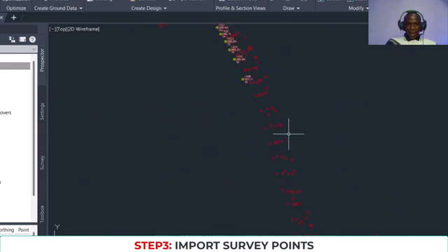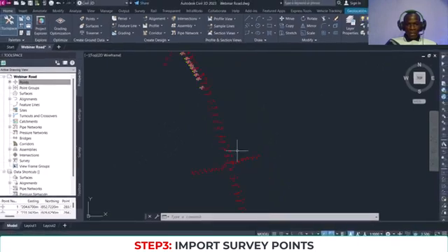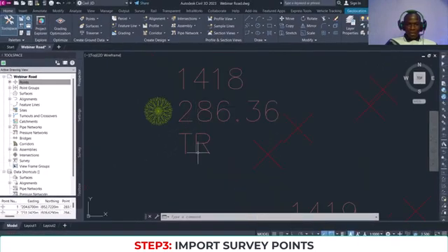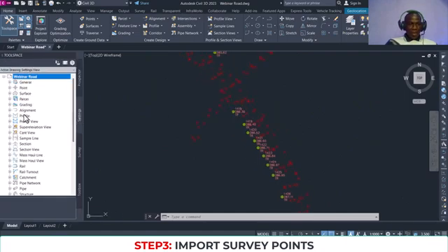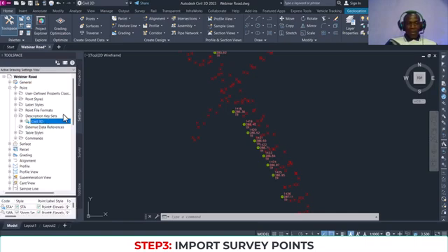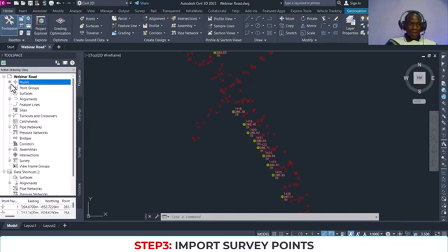Right now you don't see the descriptions of the points. You can add the descriptions to the points. It's only 3 points where you can see descriptions. That's because of what we call description key sets. Under the settings, under Points, you'll find Description Key Sets. This is where you find it, but I'm not going into that. Let's just go on. I don't want to complicate this, please. Let's just go. It's simple.